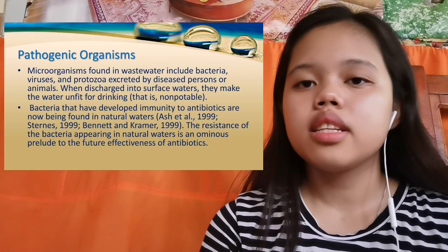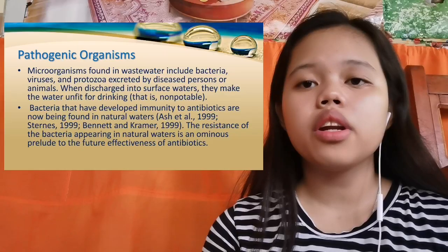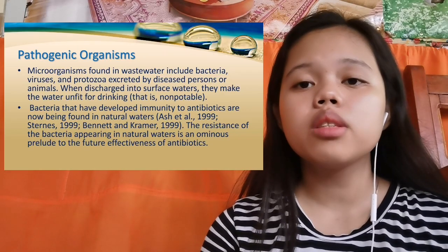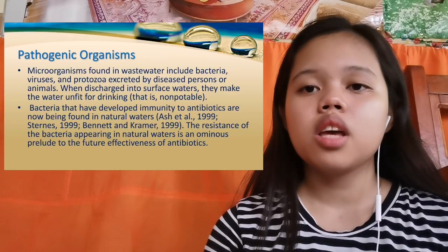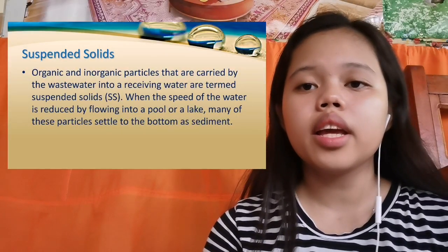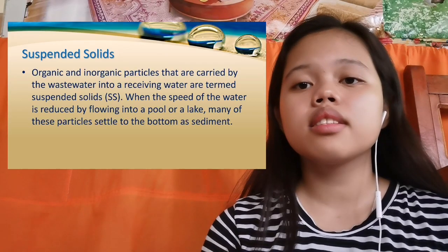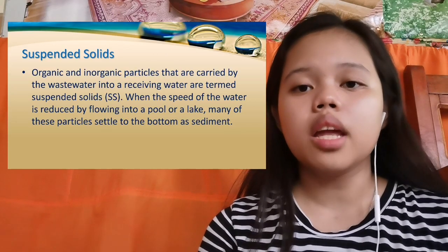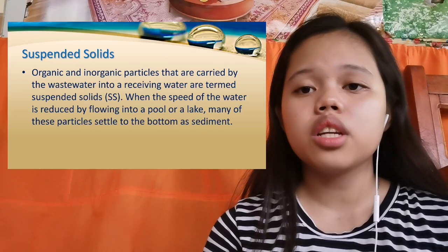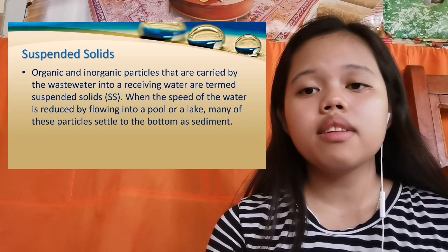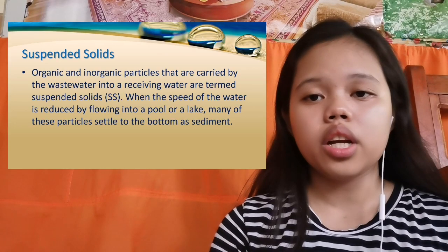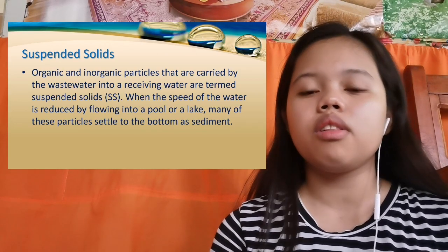Suspended solids. Organic and inorganic particles that are carried by the wastewater into a receiving water are termed suspended solids. When the speed of the water is reduced by flowing into a pool or a lake, many of these particles settle to the bottom as sediment. In common usage, the word sediment also includes eroded soil particles that are being carried by water even if they have not yet settled.